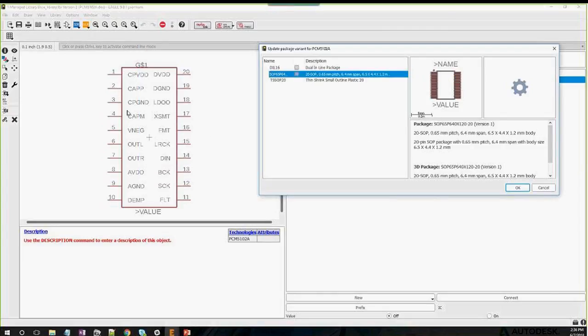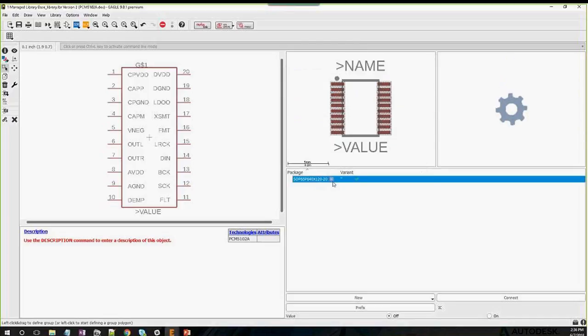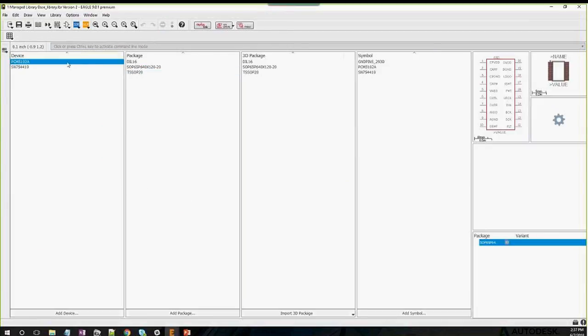So if you look here, we shouldn't see any of these numbers change once I do this replace. So I'll say OK, and there we are. All the numbers stayed the same, but now we have it mapped to 3D. This is a new feature that came in, and it makes it really easy to swap out an old non-connected 3D part to a new package that contains a 3D footprint. So that's pretty sweet. So we can go back to the library contents table of contents view.